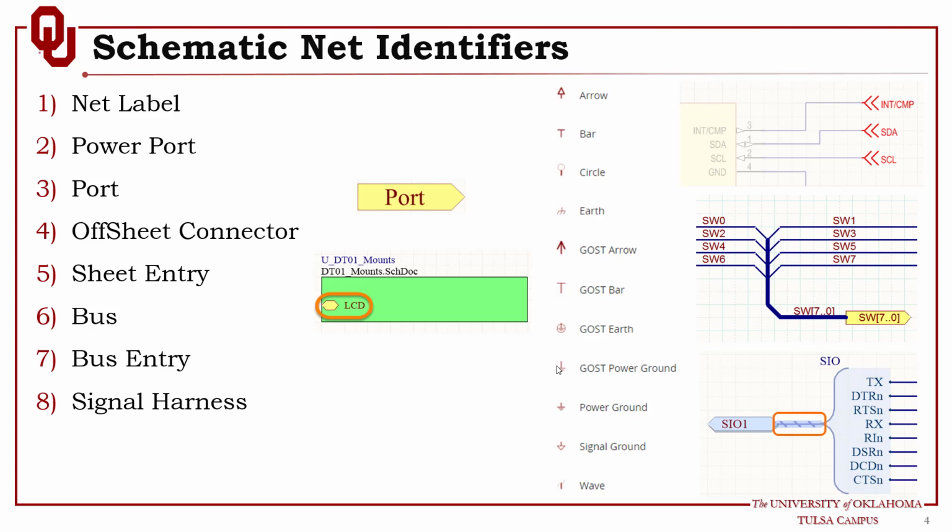They don't look at the structure you are using, whether it's global or local; it doesn't matter. Power ports have their own characteristic and they connect everything with the same name. So even if the symbol is different but the name is the same, they still connect. The property the software uses to connect these power ports is the name of the power port.